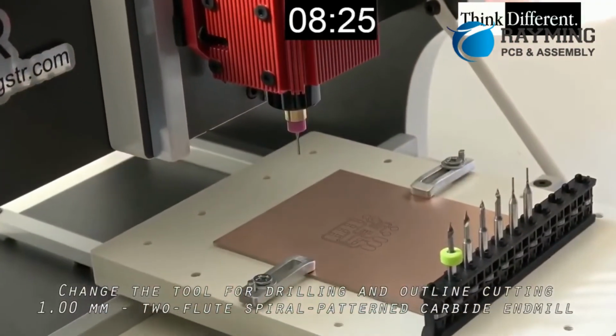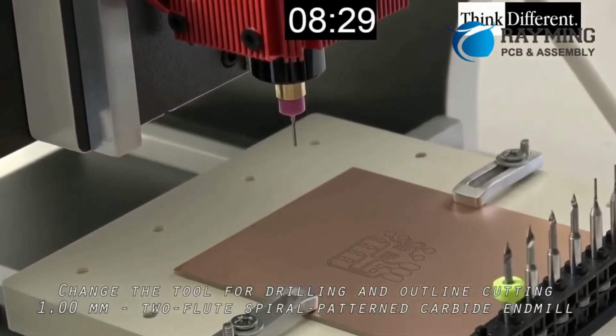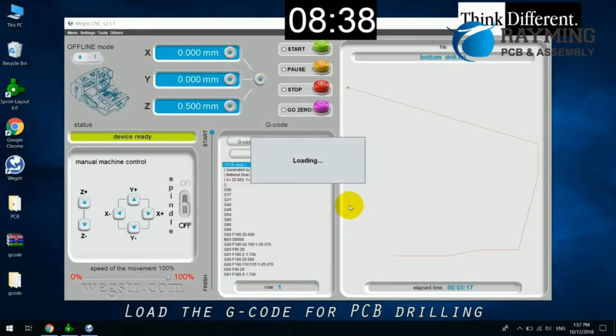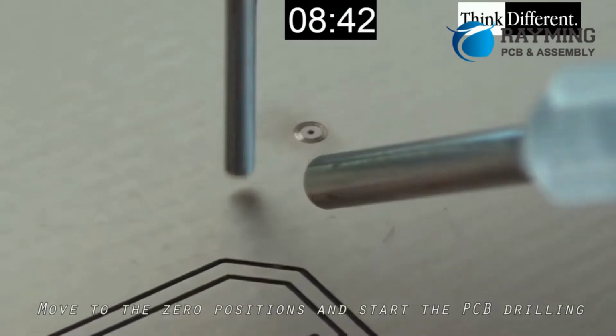First, you must decide which components you are going to place on the PCB. For example, you might place the power switch near the volume potentiometer. For larger circuits, you may want to use 2 copper layers and route the traces on both sides of the board. It's also a good idea to label the components so that you can see their labels when complete.